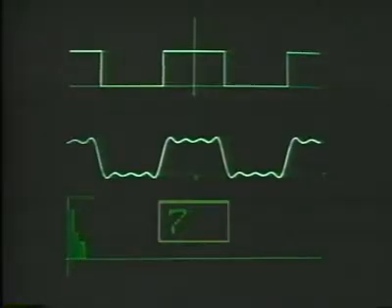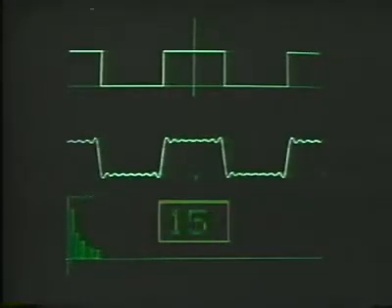So here we have the vertical scale expanded, and now what we'll do is increase the number of terms in the Fourier series and watch the energy in the error decreasing, always decreasing, of course, on the inclusion of the odd numbered terms and not on the inclusion of the even numbered terms because of the fact that it's an odd harmonic function.